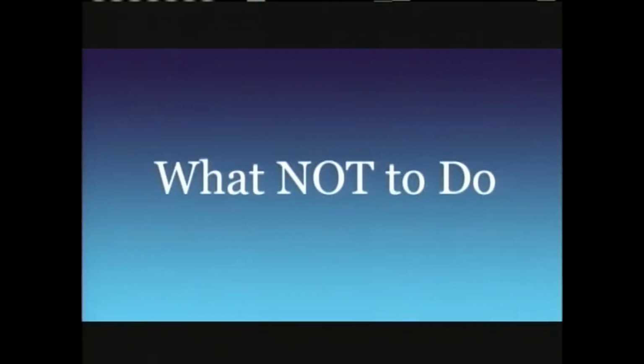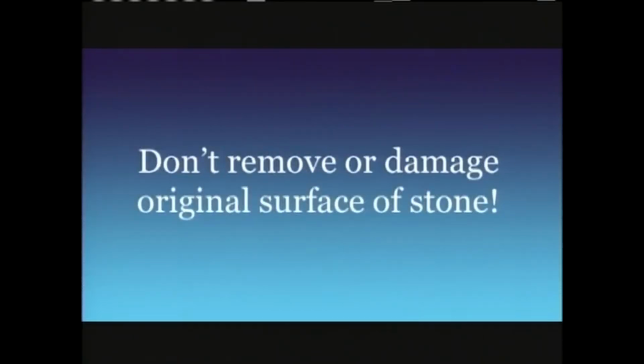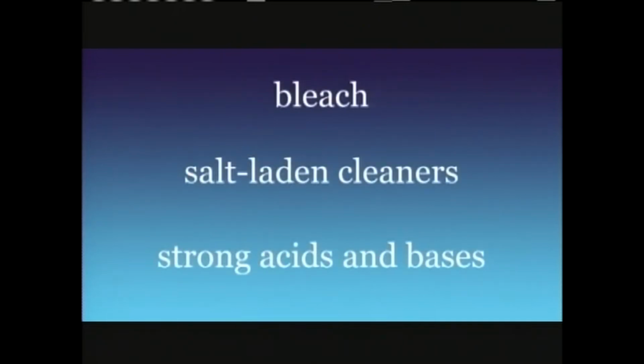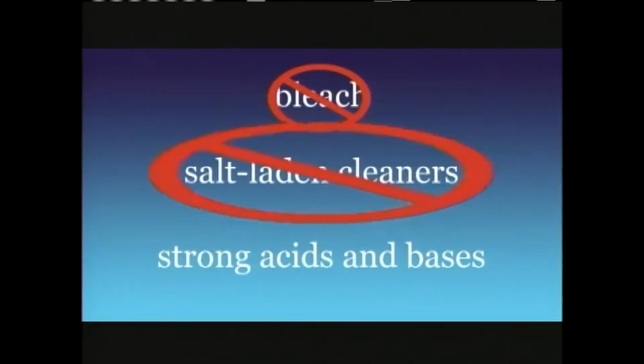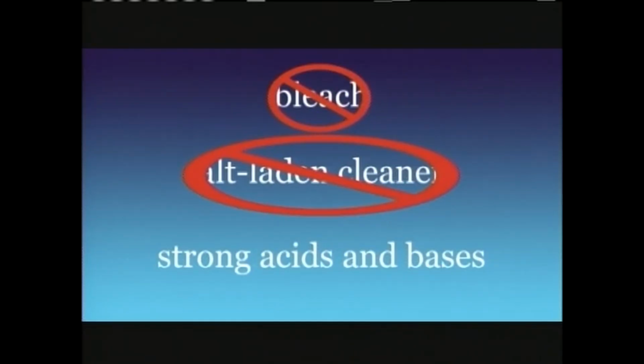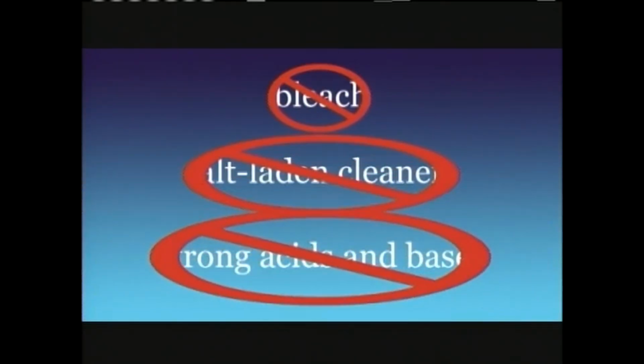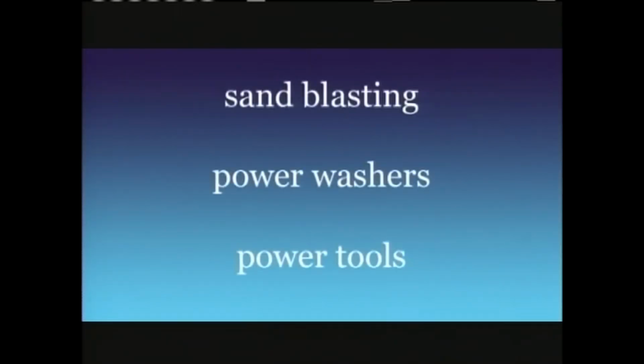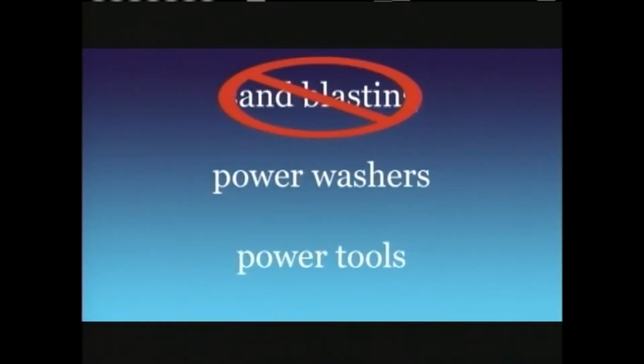Now before we get started, let's briefly go over what not to do. We don't want to do anything that will remove or damage the original surface of the stone. We never recommend the use of bleach or other salt-laden cleaners. It is also never advisable to use any strong acids or bases. Finally, you don't want to use any harsh mechanical devices such as sandblasting, high-pressure power washers, or power tools such as grinders or drills equipped with wire brushes. All of these methods can damage the grave marker.